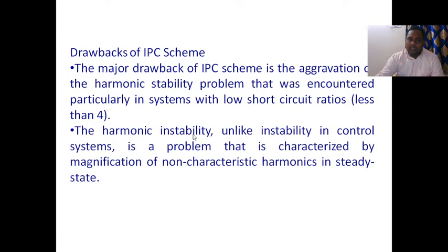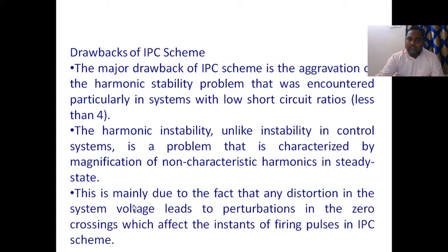The harmonic instability, unlike instability in the control system, is a problem characterized by magnification of non-characteristic harmonics in steady state. This is mainly due to the fact that any distortion in the system voltage leads to distortion in the zero crossing, which affects the instant of firing pulses in the IPC scheme.